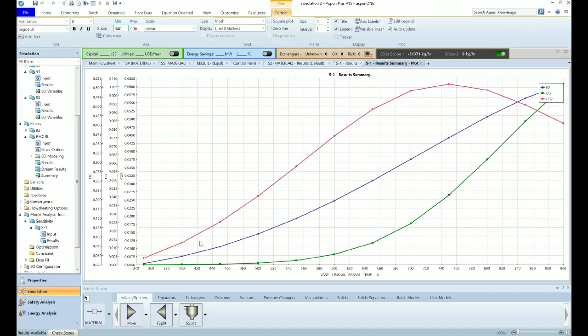this graphic to understand that here we have a maximum of CO2 production in this condition. The hydrogen is increasing with the temperature in the reactor if I change and select different temperatures for this reactor, and also the CO2 is increasing in this interval. Okay, so I hope you enjoyed this tool. It's very valuable for using Aspen for simulation, and we are going to practice it more in the next case. Okay, so let's go next.